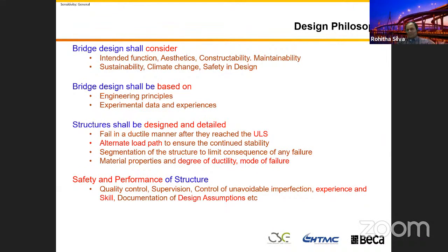This comes when you are detailing the bridge. For example, I think a couple of times when I explained it to you, there was a lateral restraint block we put on a bridge. Another thing, when we go into detail later on the bridge design, you can see we put earthquake buffers in the bridges at the end to make sure that that sort of thing won't happen.